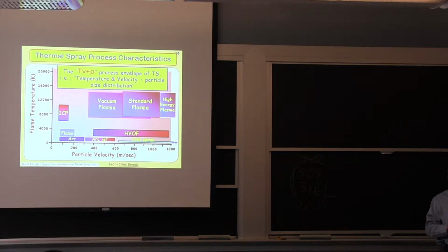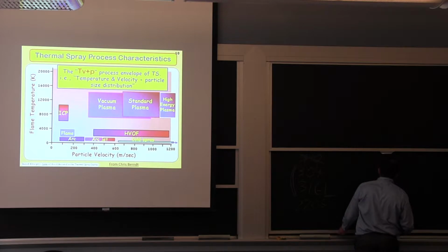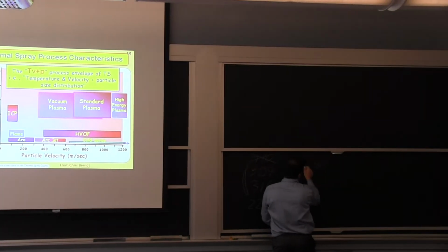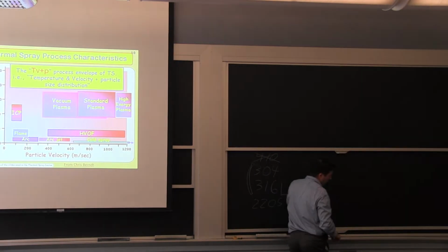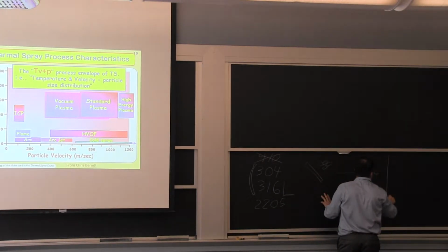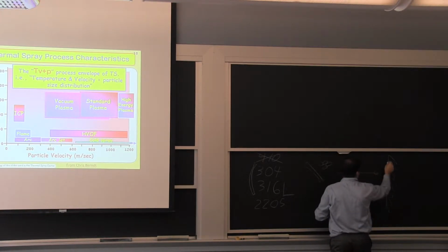So if I come each time and take a powder, the thermal spray process, the bottom line is you have a powder or wire. You heat it up always, and then you send it to the surface at relatively high speed depending on the conditions. So say this is my substrate. And typically it's going to form these little splats, they call them, and you can build them up one after the other.